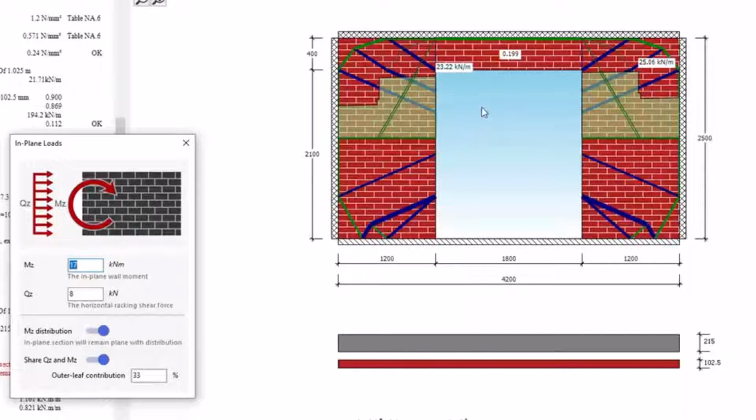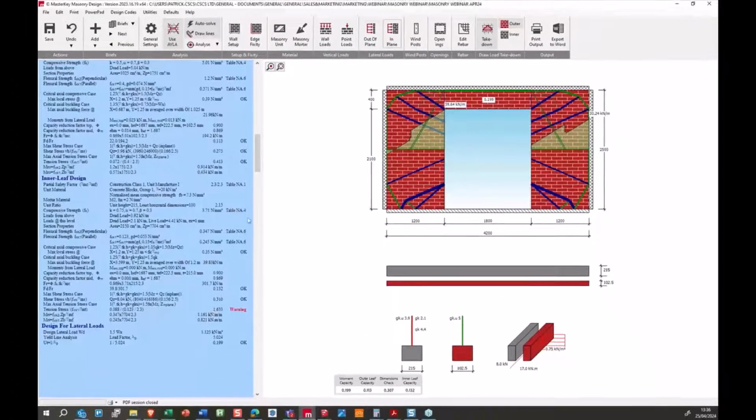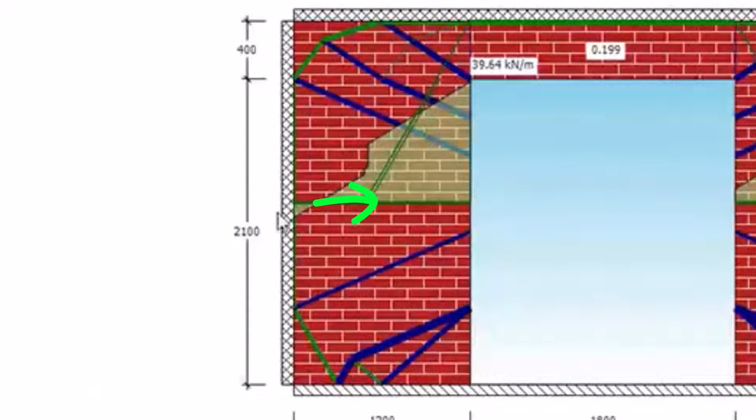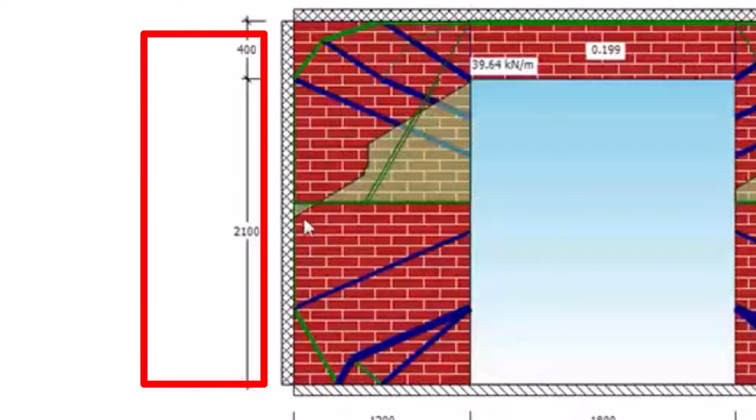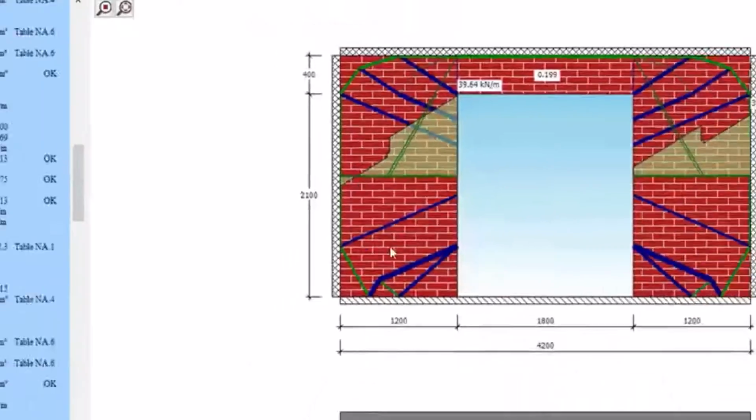If you just had a small opening, for example, you might want to keep that on so that the wall panel is acting as one. So this side's in tension, this side's in compression, but we want to make sure that the moment's shared between both. So let's say with this failure, we could maybe go ahead and specify a steel frame, but potentially some engineering judgment can come into play here, as we can assume that the load will redistribute to the compression zone in the ultimate state. So we're also ignoring the effect of the return on the wall. So it's a very small local tension stress, and we're not assuming any cracking here. If you were to assume some cracking and some redistribution of the moment there in the compression zone, you might assume a pass on this.